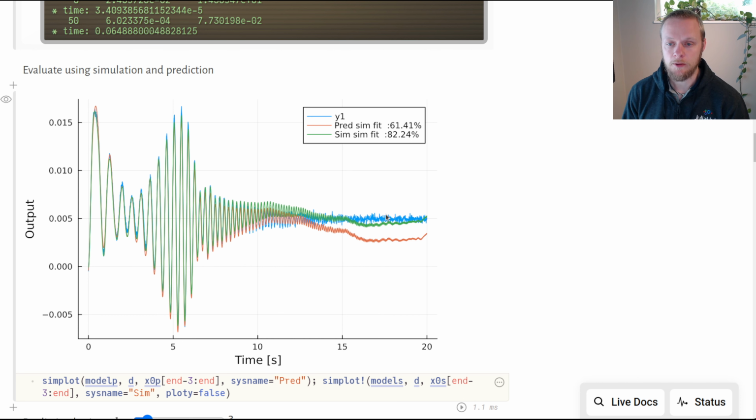Where the input is torque or force, and that's integrated twice to get position. And due to the small amount of Coulomb friction, so this non-linear friction that can't be represented by a linear model, if we integrate a small error twice, we will get a drift. If we integrate it once, we will get a drift, and if we integrate it twice, we will get kind of an even worse drift, right?